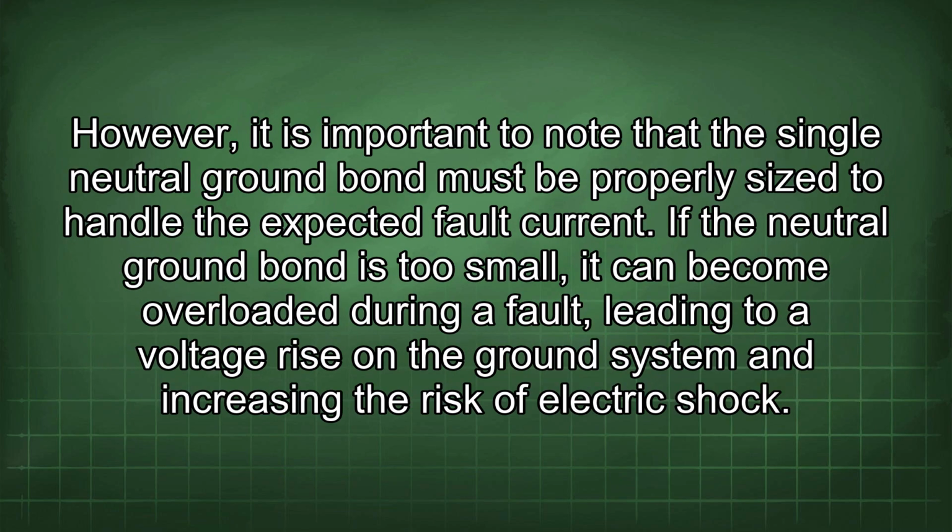However, it is important to note that the single neutral ground bond must be properly sized to handle the expected fault current. If the neutral ground bond is too small, it can become overloaded during a fault, leading to a voltage rise in the ground system and increasing the risk of electric shock.